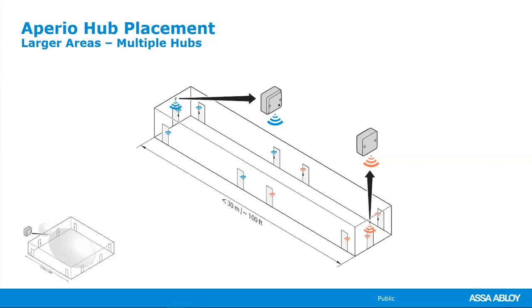Moving into a long hallway, like I mentioned before, with the RS-485, you have the ability to daisy chain or link those hubs together. So in this case, we have a 100-foot hallway. Let's say you initially put the hub that's marked in blue, you install that, and that's running these 5 doors. Maybe 6 months later, a year later, you decide to add these additional doors. All you would need to do is tie into the existing hub, run your new hub placement, and install those doors. And now you have access control for that whole hallway, and you only had to run 1 cable for that installation.